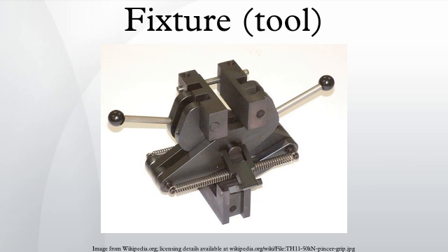Fixtures must be designed such that the pressure or motion of the machining operation is directed primarily against the solid component of the fixture. This reduces the likelihood that the fixture will fail, interrupting the operation and potentially causing damage to infrastructure, components, or operators.